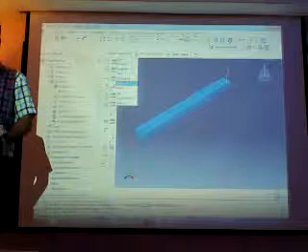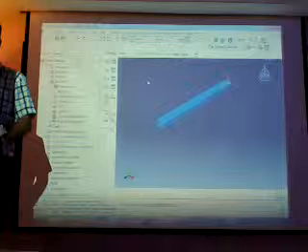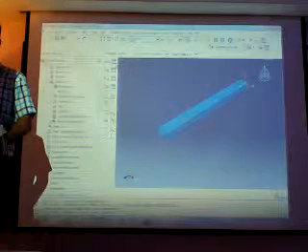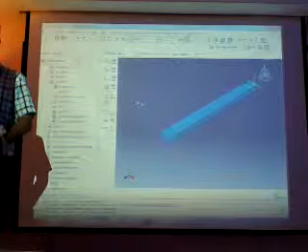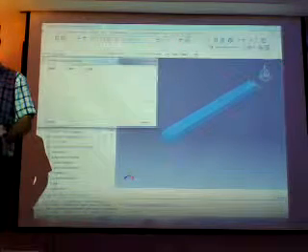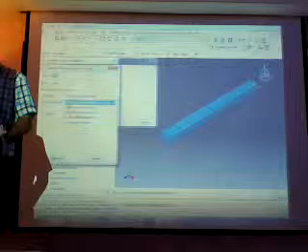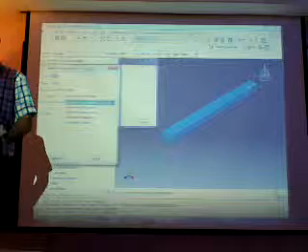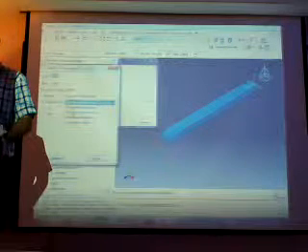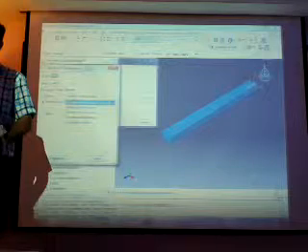After interaction, we have a load part. Here we define our boundary condition and our load. First icon is the load, second one is the boundary condition. First, we define a boundary condition, create, and we take first one, symmetry. That's depend on your simulation. You can take any of them depend on your simulation. Now we need first one.